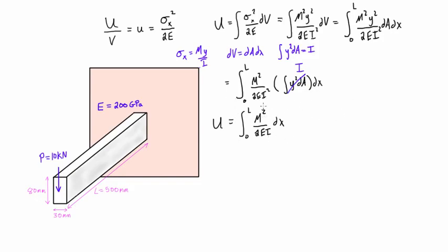But when we look at this M squared up here, M is actually the equation for the moment in terms of x. So unless you're in pure bending, this expression won't be constant. We could write, like, M of x, but I don't really like doing that because I'm going to get confused about whether or not that's an x term or the expression including x.